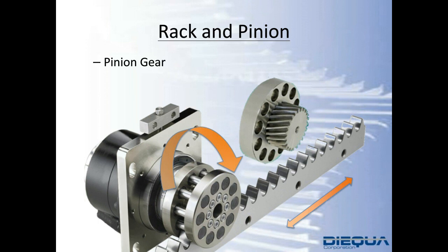When you are driving a pinion gear along the length of a rack, you have separation forces as you're trying to drive forward. If you were to simply leave a reducer with the pinion gear as you're driving without securing it to a frame, the pinion gear and the rack would separate after, let's say, a few inches of travel. Having the roller type improves efficiency, and it helps with speed.